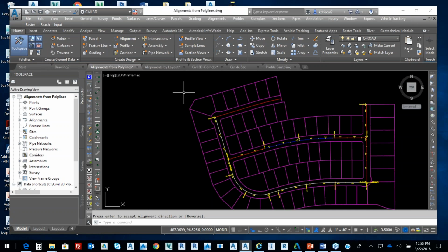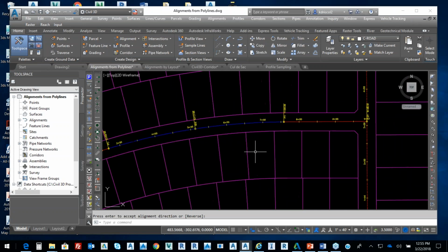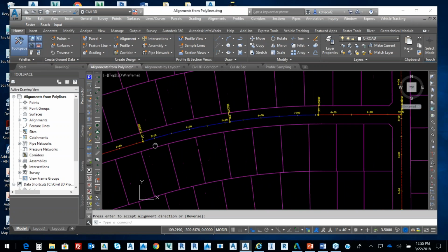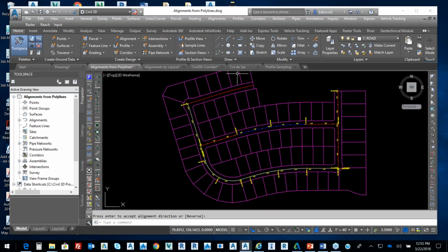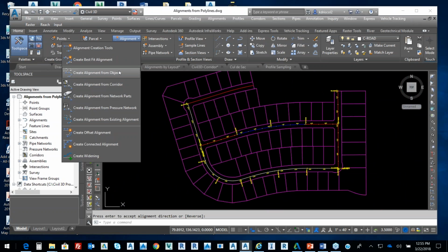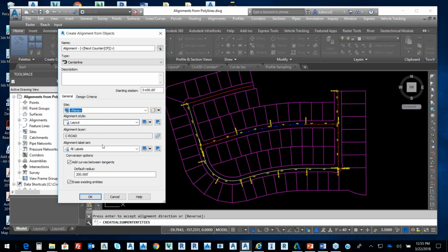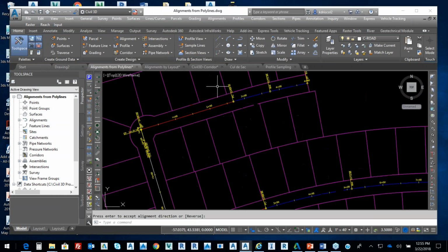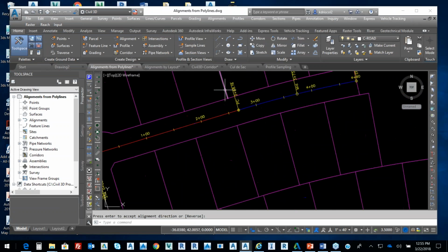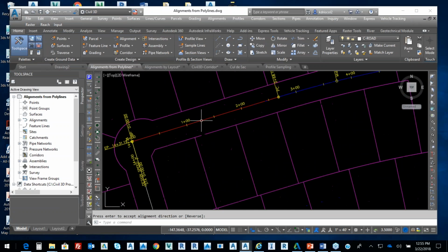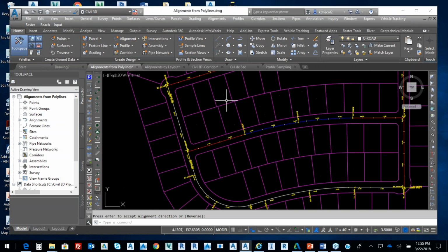I like that. So from that layout style, we should be coming from left to right. So my last alignment, pretty straightforward. I pick on my alignment, right click, hit enter. We're going to do my layout style and select OK. So there's my layout style for my alignment. And it's going from left to right.